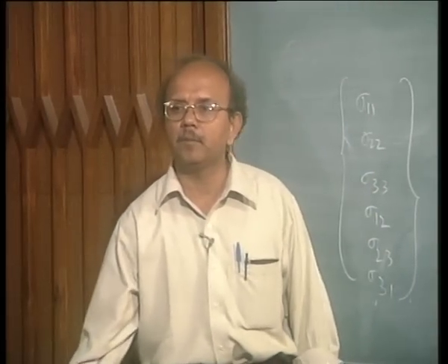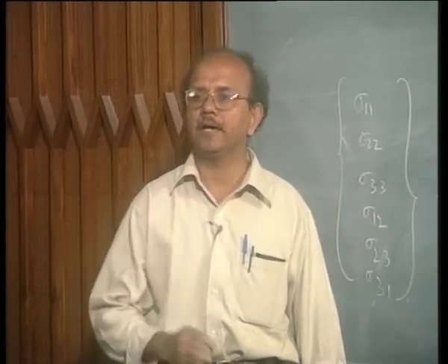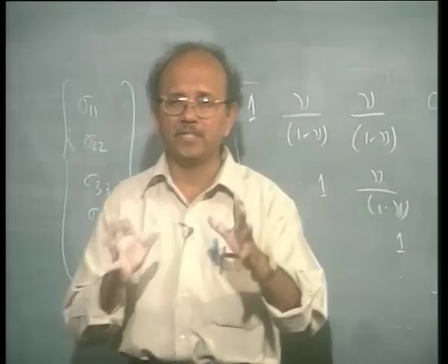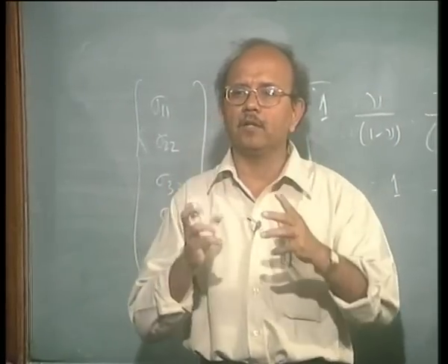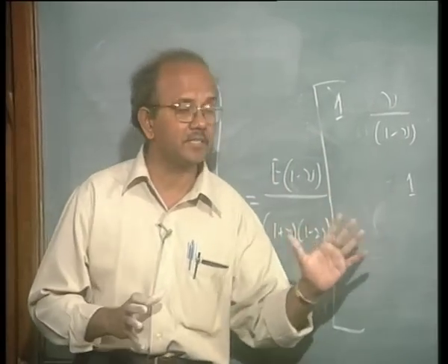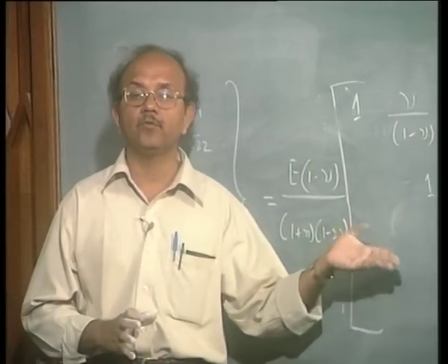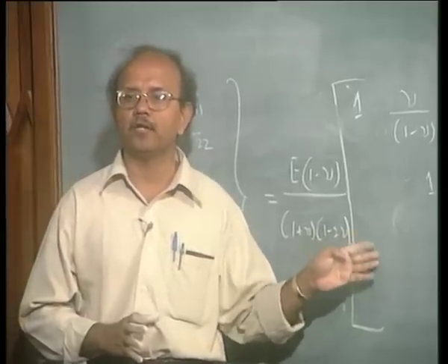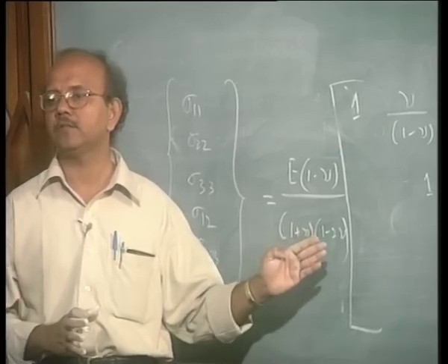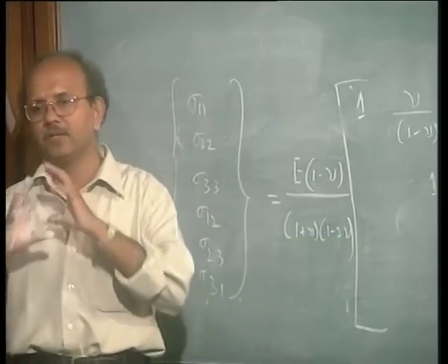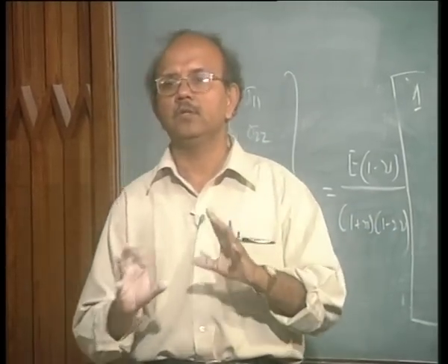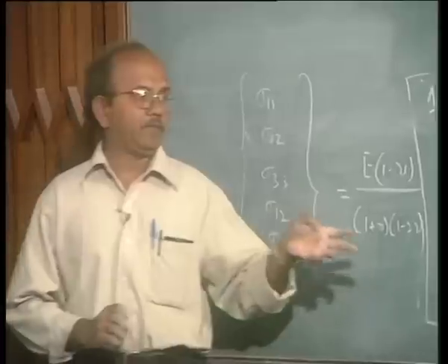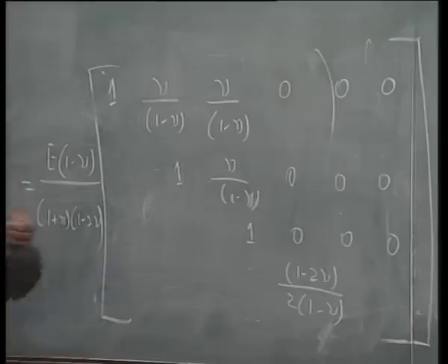In fact, the whole finite element modeling rests on concepts like that. No doubt they are outside the view of finite elements per se, but in order to do a model, you have to come to this extent to understand what this is. Now, if you wrongly write nu is equal to 0.5, then definitely you know that you are getting into trouble. That is why you should know this kind of equation. And there are special tricks of the trade that you will use in order to satisfy this constraint called incompressibility, but if time permits, we will come to those tricks later in the course.